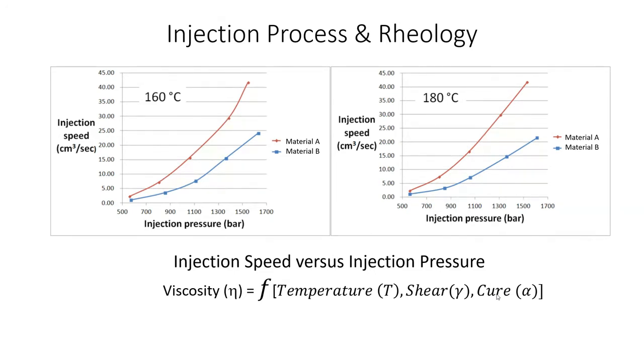And as the material flows in, there's stagnant points, and there's the parts that move faster and slower, and therefore the energy of the tool, the heat, is through thermodynamics being soaked into the rubber, so to speak. And what we see is an onset of cure during the flow-in process. During cavity fill, we often see the onset of cure.